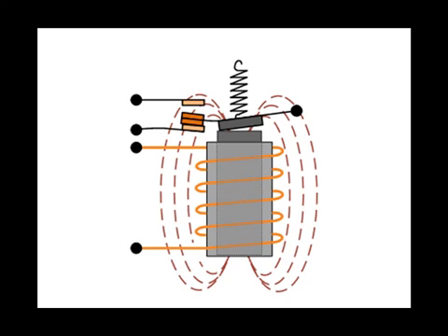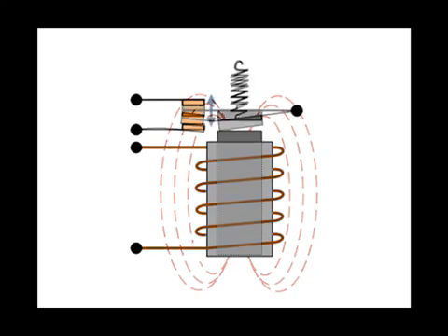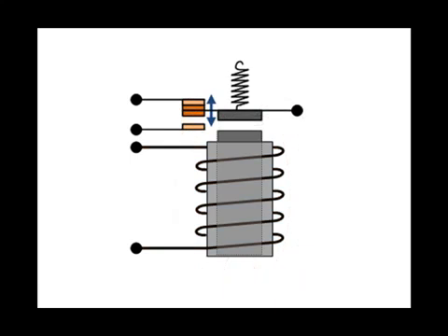When the coil is de-energized, the spring tension opens this set of switch contacts, and consequently at the end of the spring travel closes another set of contacts. As this presentation continues, it will become apparent why a short discussion on relays will bring a more clear understanding of programmable logic controllers. The programming language used to create or write programs for a PLC, programmable logic controller, is based upon relay circuit symbols.